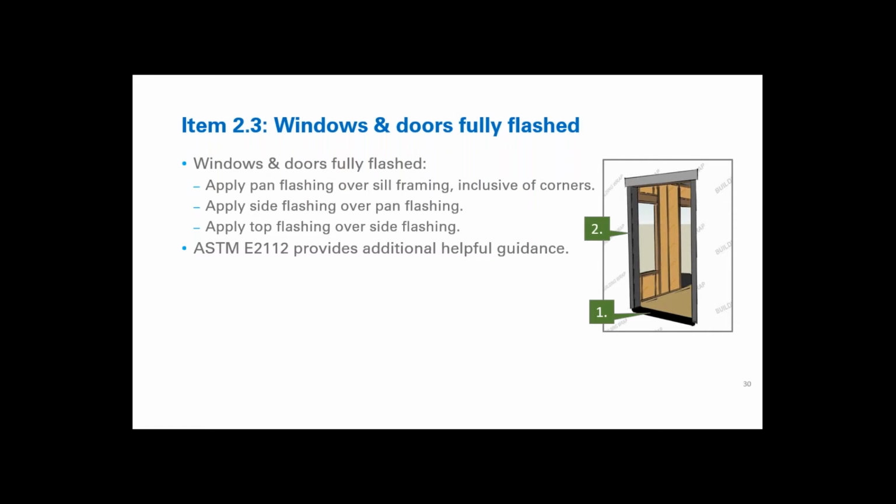So work from the bottom up. And then number 3, apply the top flashing over the side flashing. So this is going to ensure that you've got everything flashed in the correct order and solve those weak spots.